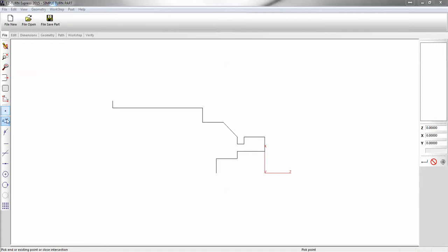Okay, to start, we can get some dimensions off of this. You could either go to dimension and label them, but I'm just going to show you a quick technique. If I put my cursor using snap to all on the position that I want to get the dimension, I left mouse click. Now it would be different when you're building a path. You want to right click twice. So when I left mouse click, it's telling me that that location was -5.5 and the X is at 5